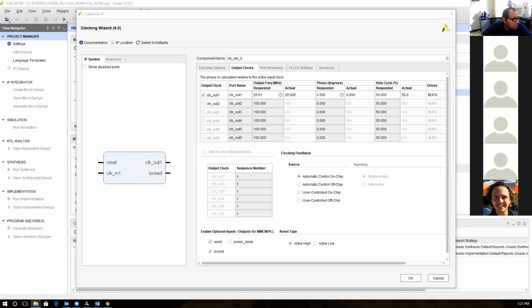It's about the VGA, the one I shared with you. Do you remember what the required clock was? I think it was 25 megahertz, but with a fraction. Was it 25.01 or 25.1? Well, there is nothing to hurt, I would just do it like this. And let's make a name and call it VGA clock.